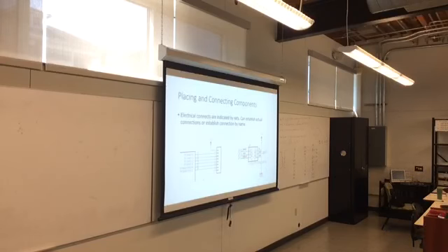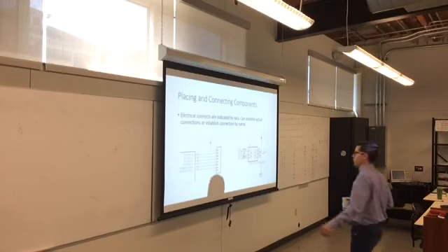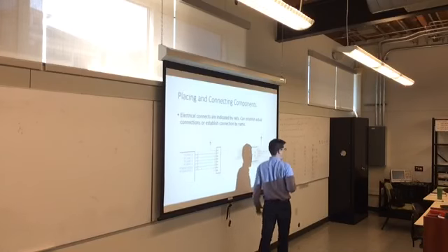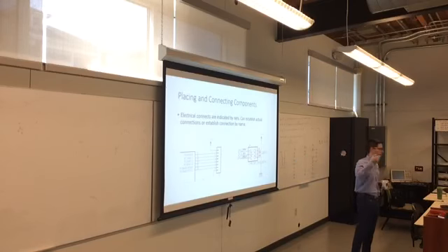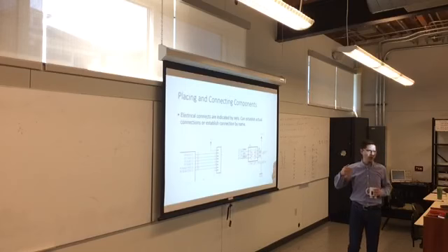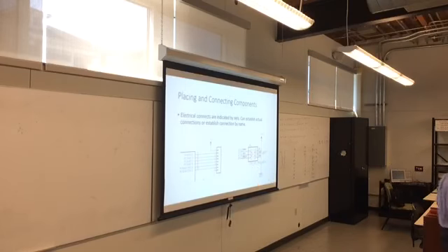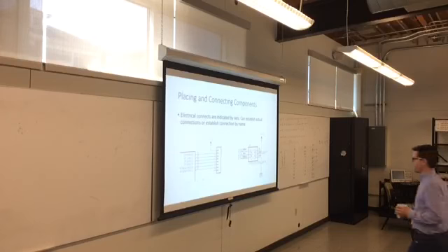Now, when you are doing the schematic, when you're connecting up your design, you are establishing nets. You are establishing nets between ports on devices. A net is a logical connection. It does not actually say where that wire should go. One funny bug in Eagle is that there's a net tool and a wire tool, and they look exactly the same. But if you use a wire tool, you're actually drawing a wire on the schematic, which is bad, whereas a net is making a logical connection.